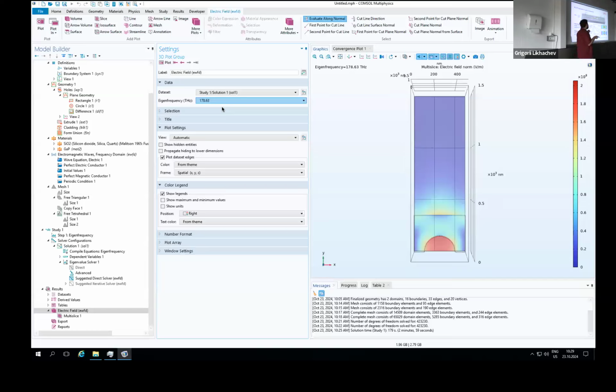What you can do here is pick a normal dispersion waveguide in the middle that is larger to minimize the losses in the biggest part of the resonator. This is not up to scale: these things are like 15 microns, and this is like 1 millimeter, 500 microns. So you can reduce the losses by picking a wider waveguide, but by designing the mirrors such that they contribute anomalous dispersion, you can still get anomalous dispersion overall.